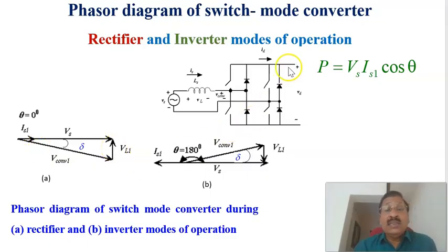Now, if you adjust the converter voltage, this is the second case. Converter 1 fundamental voltage is made to lead the Vs. Second case here. You can see that one. Then, in order to get this vectorial sum of V converter 1 plus VL1, that is the total voltage, the supply Vs input voltage, AC voltage. Here we can say that this is the inductor voltage, and to that one the current will be perpendicular.